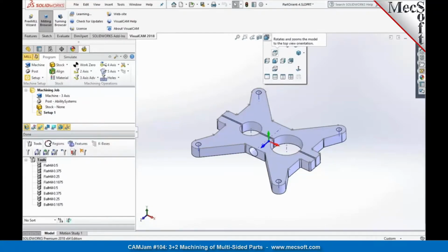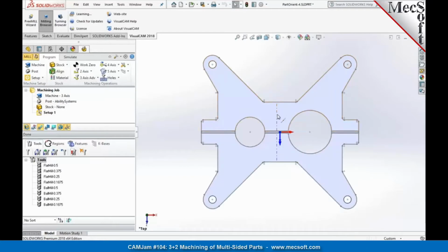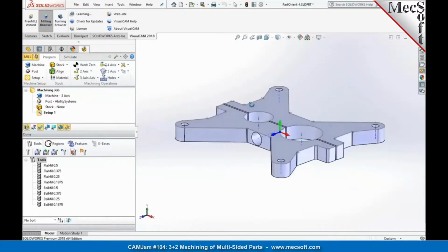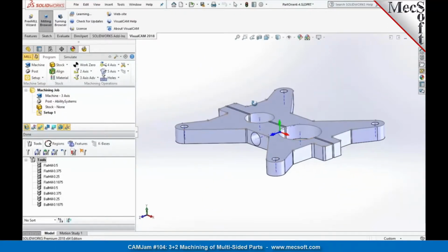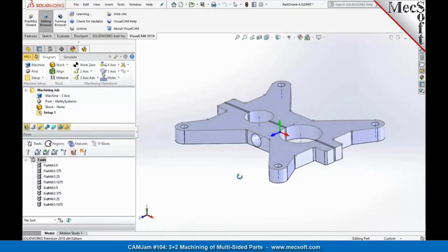So when you go into the top plane, you're noticing that this is your X and Z axis. Typically when you model a part in SOLIDWORKS, you'll be starting out from the top plane, and you'll notice that the coordinate system that you see here is automatically coincident with the world coordinate system of your host CAD system, which in this case happens to be SOLIDWORKS.